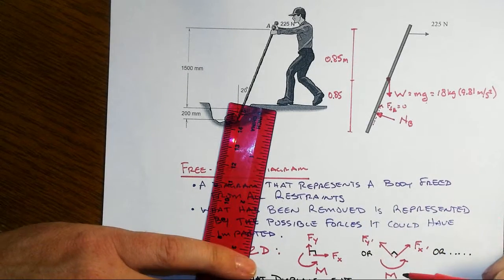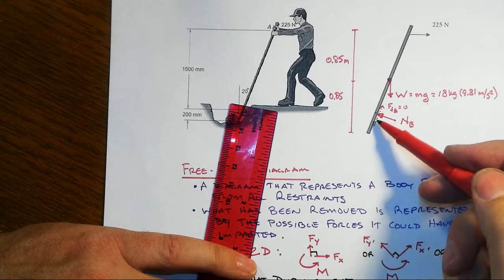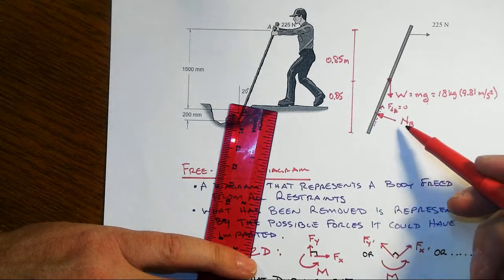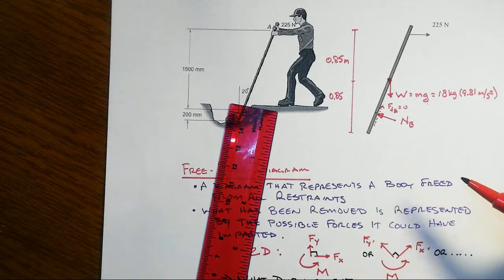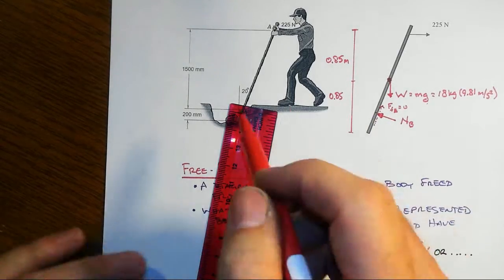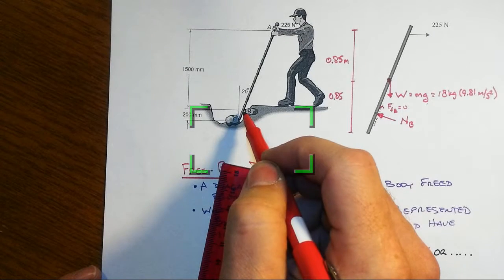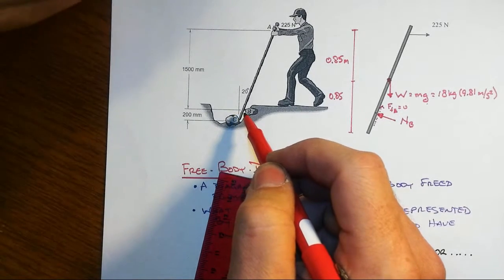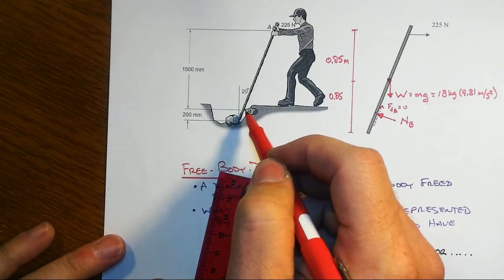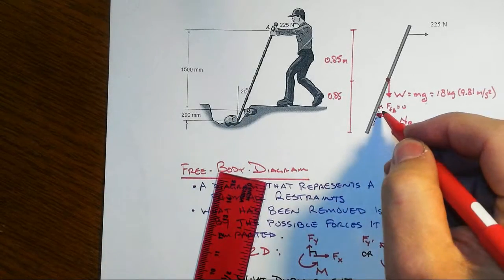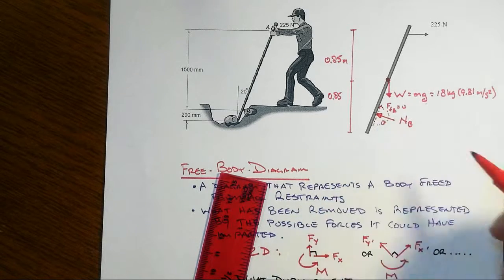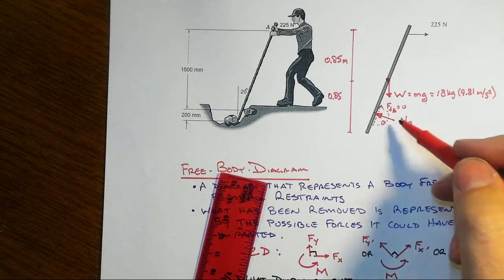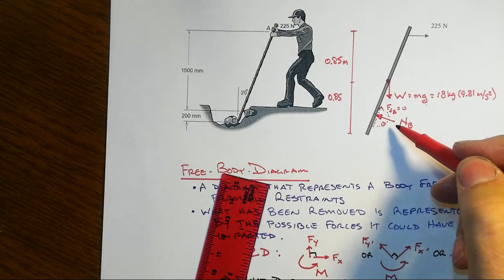Now then you say, okay, so we're not restricting displacement along the shaft. We are restricting displacement at point B perpendicular to the shaft or the prybar. What about rotation? That's the critical part about this coming to a point. There's nothing here that prevents rotation here. So there's going to be no moment showing. I'll go ahead and show a dashed line. It's 0 also. We only have one unknown here.